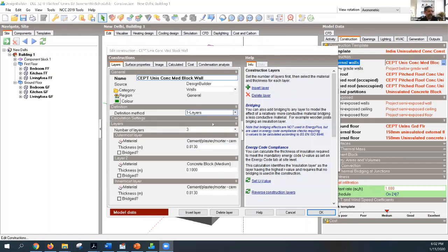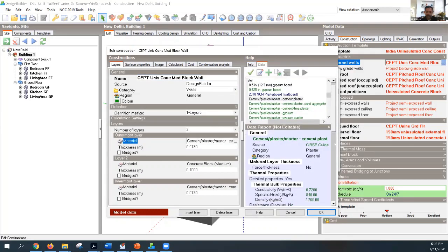Thank you. So I was saying, this is your external wall. It's made up of 3 layers, and each layer is a material. That material has physical properties of conductivity, specific heat, and density. If you have defined layers made up of defined materials, which have these values behind them, no problem. But if you are making a concrete mix which has cow dung in it, and sand in it, and Busca in it, whatever, then you need to take it to